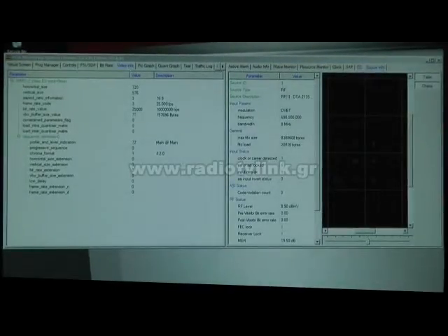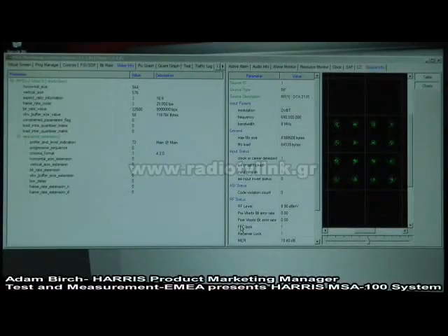Let's go with that one. So as you can see here, this is from a DVB-T source, and you can see here that there's a full constellation diagram, so you have a QAM 16. And each stream gives you individual information and individual data on what you've got there.